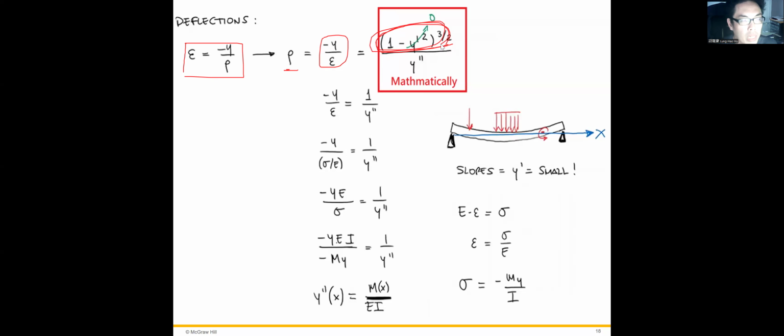So here I'm not going to work through the math. I wanted you to know the mathematical definition of the radius of curvature. Okay, so this term we can ignore because it's the derivative of y prime, the deflection. As I mentioned previously, it is the elastic deformation. Therefore, the deformation is very small. After you square it, we can regard it as zero.